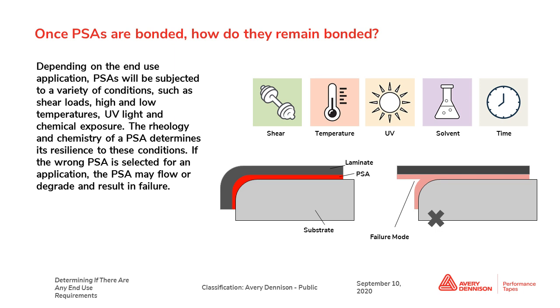As you can imagine, that foam is going to have some internal strength, and it's actually going to want to return to a flat state. But you have the PSA there preventing that from happening. But that foam might be applying stress or shear resistance on that PSA.